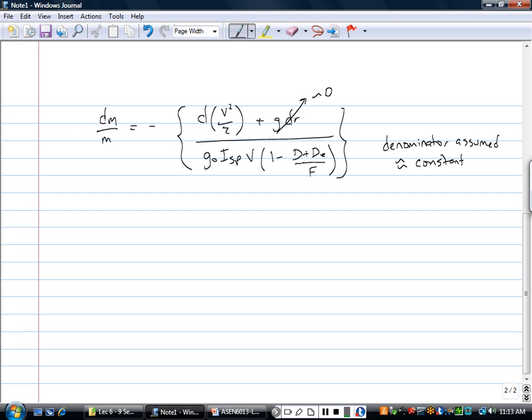As we saw before for low Earth orbit, it was about a 20-to-1 ratio, so it's a reasonably good assumption to make life easy. We're also going to assume our initial velocity is much less than our final velocity. So when we do this, we can just get down to our final velocity term. All these assumptions are essentially the same as we did before. Mass final over mass initial is the exponential of minus V final divided by our rocket terms.